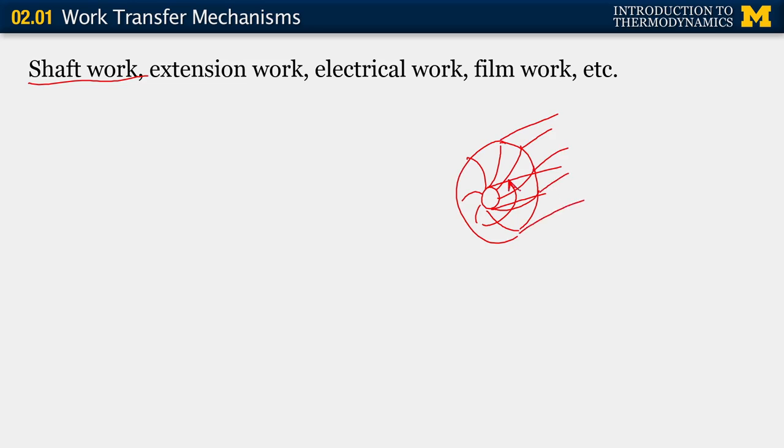But what we want to show is that we have a shaft that transfers that energy, and it's rotating. And so we go back to our general description of work, which is equal to the force times the distance over which it's executed. In this case, the force that's executed is a tangential force because we have a rotating piece of machinery. And so we define that as a tangential force.